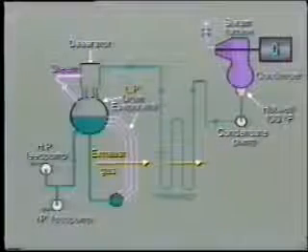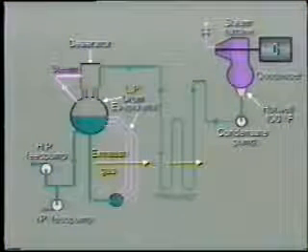Remember, steam generation does take place in the LP section, and it is this steam which is supplied to the de-aerator to remove the oxygen and other incondensable gases. The level of water in the drum or storage tank is maintained by the feed water control valve.